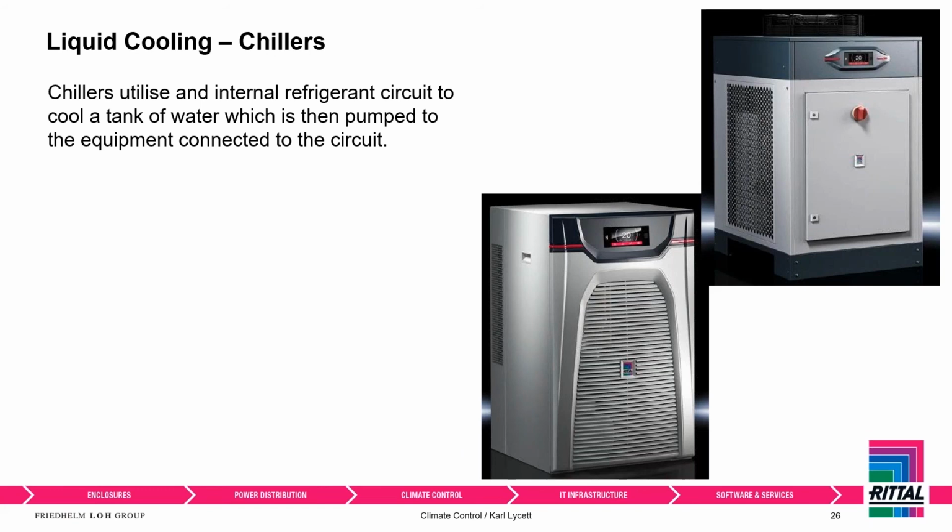So the air-to-water heat exchanger needs to be supplied by something, and that's where the chillers come in. We also manufacture, very proudly, these chillers that are designed and manufactured by Rittal. These are basically a cooling unit in a box. Instead of cooling hot air and blowing it into an enclosure, they're just cooling that tank of water that I referenced in the previous slide.